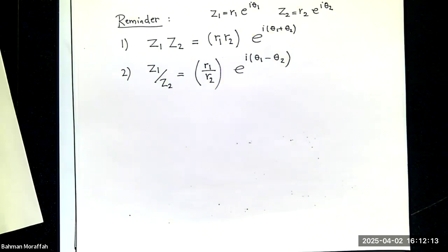Next lecture, we're going to continue on this and do a few more examples. But essentially, that's what it is. We go from the time domain to the frequency domain, replace everything by its equivalent, solve the circuit in the frequency domain, and convert it back to time. All right? I'll see you guys Monday.